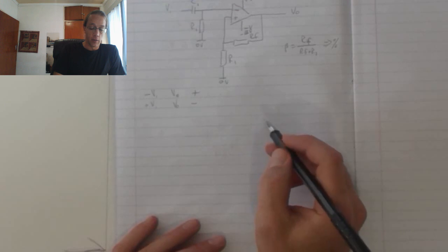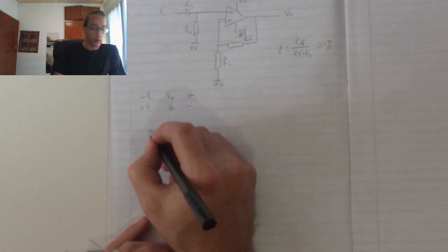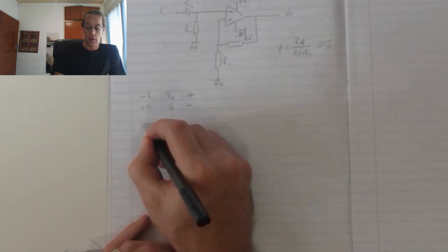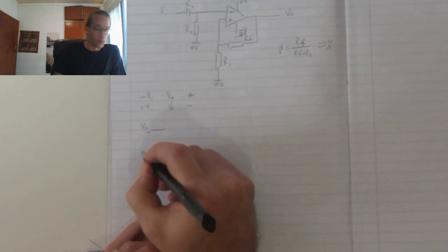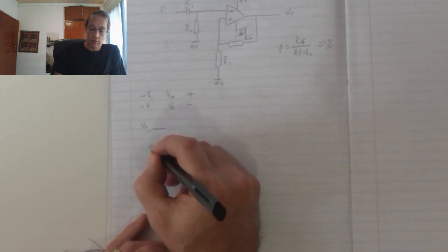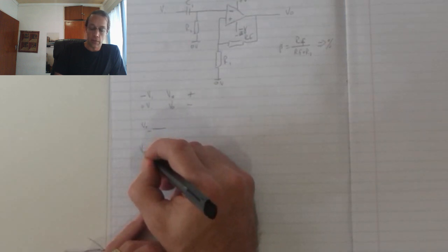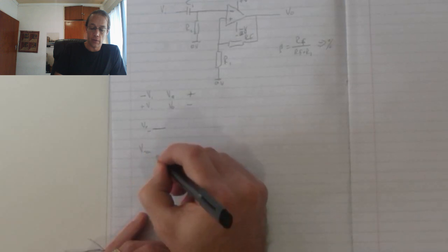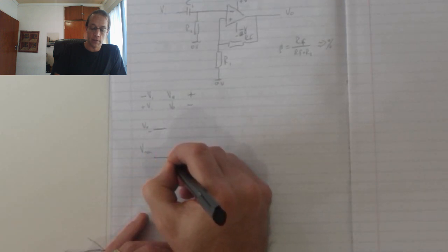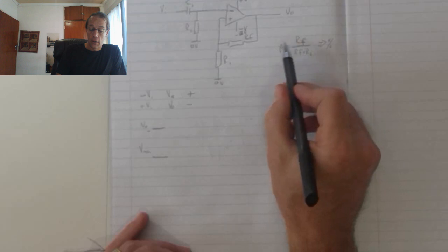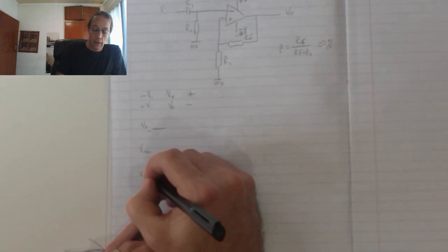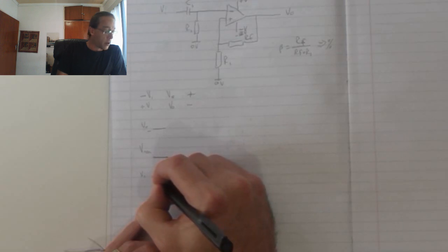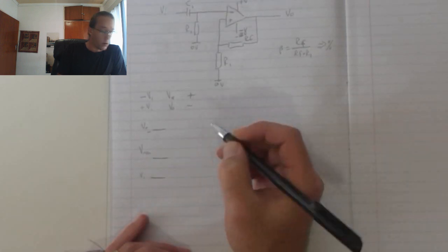So looking at the inputs, let us accept that we've got a negative voltage on my output. Because of that, my voltage on my non-inverting input is also negative at the percentage set by this ratio, and my V in, because there's no signal connected, is 0.